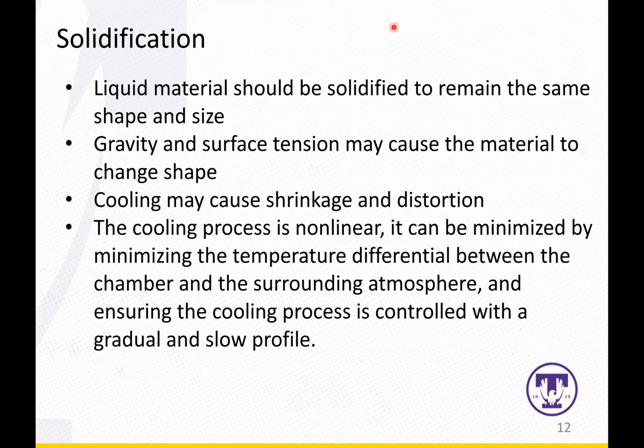So there must be some principles, and those manufacturers of the FDM machine, I believe they did a lot of tests and tried to find some optimal solutions for the size and the pressure to apply on the nozzle. And cooling may cause shrinkage and distortion, and that is, I would say, quite common for those thermoplastic materials, right? So there is always shrinkage and distortion for thermoplastic material during the cooling process.